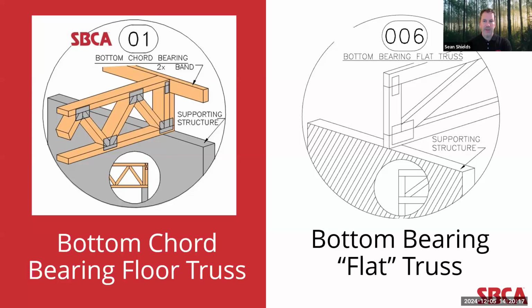Now, the biggest difference is that the wood members are oriented 2x4 in the roof truss, which is typical for roof truss construction. They're not oriented in the 4x2 orientation that is typical of floor trusses. And that's important to point out just from a structural standpoint. 2x4 puts the wood along its stronger axis. So again, the loads are transferring through the wood members in their stronger axis, or basically the thicker portion of the wood, which typically allows parallel chord trusses, roof trusses that are flat, at the same depth, to span longer distances because, again, the wood is in its stronger axis.